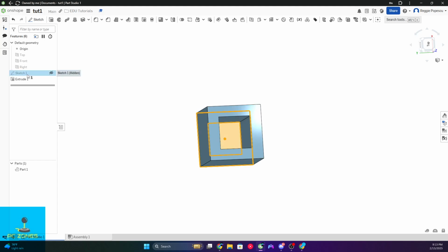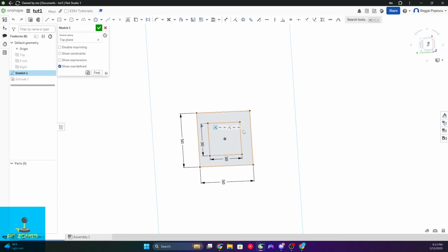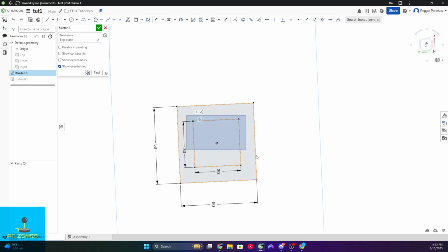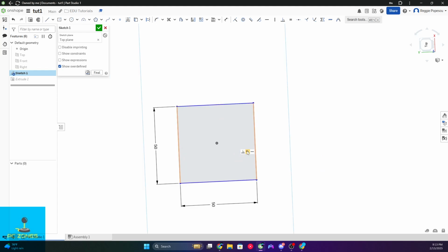And then let's say I want to make it a bit more complicated, I'll go to edit, and I would select this inside, and I'll just remove it like that by pressing delete. I will add a circle by selecting this one here, center point, or you can go for different ones, 3-point circle, ellipse. Sorry guys. So 3-point circle, you would drag from the center and you will select 3 points of how you want your circle, which is not going to be symmetric. So I like the center point circle because a lot of objects in our world are actually circular, believe it or not.